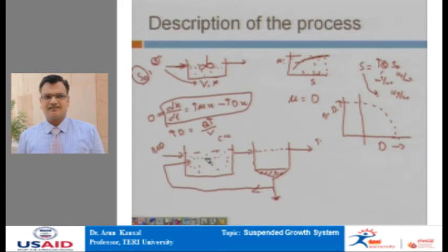That is why the process is known as the activated sludge process. The word activated sludge process means we are running this process with the use of sludge which is highly potent for the degradation of organic matter, because these are the organisms which have grown, and we are bringing them back into the system, and hence we are increasing the bacterial concentration.